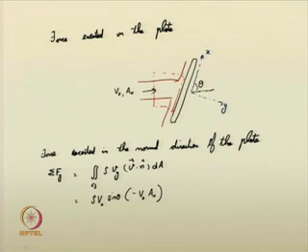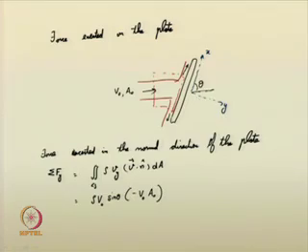You can see that the outfluxes from these particular directions are not going to create any force in the normal direction. So, the force exerted in the normal direction of the plate, that is in the y direction, is being provided only by the inlet of that control volume, whatever volume of water is coming. That is the only quantity that is providing force. Okay.